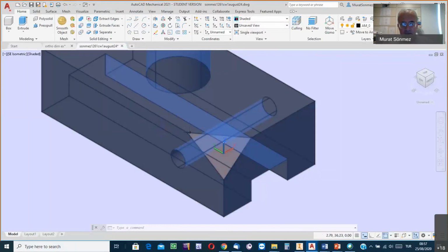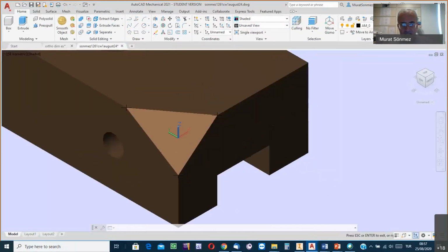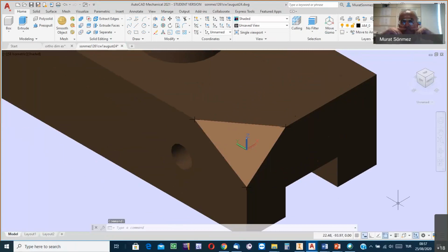Yes, we mark the points first. These are still shining. In doing this, opening a parenthesis, I said that the point style in the default configuration of AutoCAD is wrong. AutoCAD, in its default configuration, uses a dot for the points. A dot is not a distinguishable marker because it may seem as if it were a pixel point on the screen, or if the dot is along a straight line, then how can you distinguish where it is?